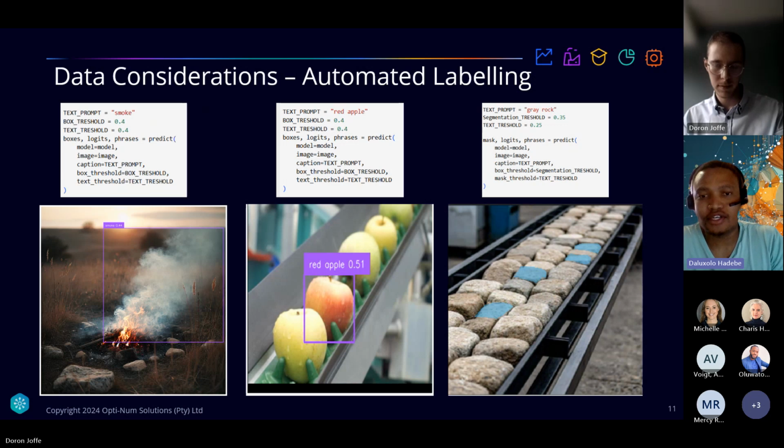And then the advantage of the MathWorks tools is that they have labeler apps where you can now more interactively deal with some of these workflows. By using Grounding DINO to create those initial labels, you could say label a person, a car, a tree in the scene, and it will try its best. Of course, there will be some misclassifications here and there. And then by connecting that with the MATLAB labeler applications, you can easily just change the label. That would typically involve a lot of resizing of some of the bounding boxes, deletions for misclassifications, or adding a bounding box that it may have missed.